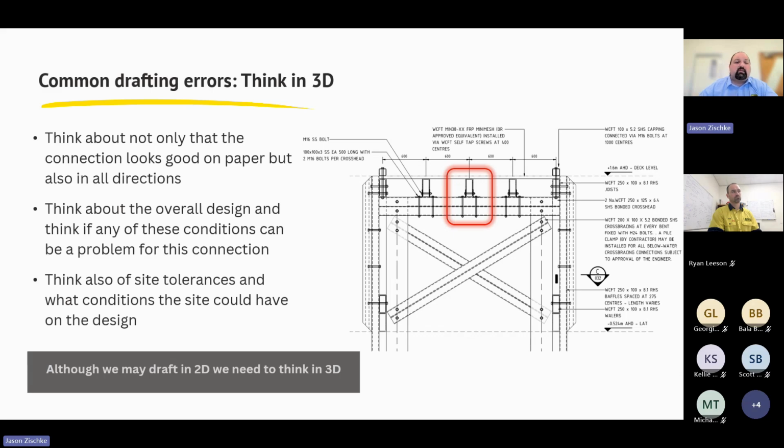Also, as the piles were driven, this meant that we had to wait for all the piles to be driven and surveyed before it could come in to be modelled, to design each of these bolted brackets, to provide that millimetre accuracy that this kind of connection would need.